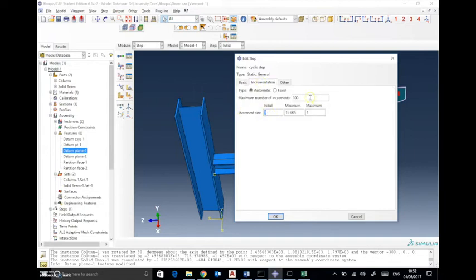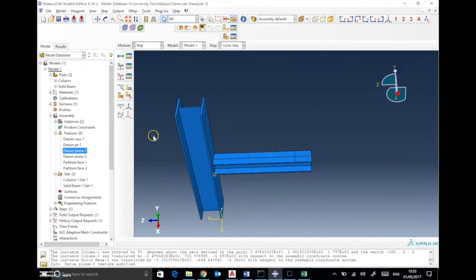And here we have to pay extra care about those 3 boxes. Here you have to make it as big increments as possible, to make sure that the analysis is completed. So I'm just going to make it 100,000 increments. And this one, I'll come back to later on when I define the amplitude. So I'm just going to accept this one for the time being. And that's great.